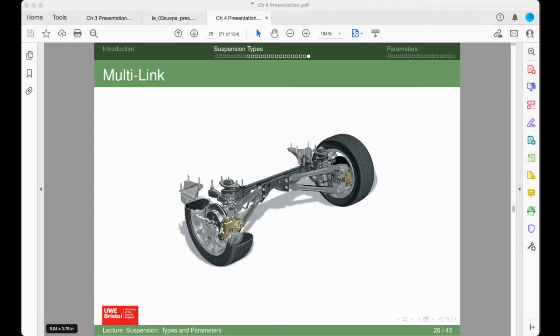What are the benefits of a semi-rigid axle over fully independent systems? Give a full explanation. What aspect of the semi-trailing arm suspension aims to improve over the trailing arm? We talked about that. It's about the camber recovery. Discuss the benefits and limitations of a strut-based suspension system, making comparisons to the more expensive double wishbone suspension system. So obviously, you look at the disadvantages of a strut-based setup compared to double wishbone. And then how does the Super Strut differ from a standard strut, and explain the differences that help minimise torque steer. Again, there might be questions around wishbone design. What are the drawbacks of a double wishbone suspension?